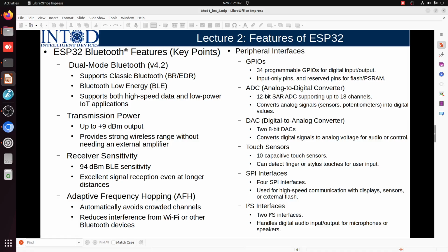The MCU can be connected to a number of SPI sensors or SPI devices. So, the MOSI, MISO and clock pins will be common to all the sensors. For chip select, one GPIO pin from the MCU will connect to the chip select pin of each of the sensors. And these pins will be used by the MCU to select which sensor it wants to communicate with.